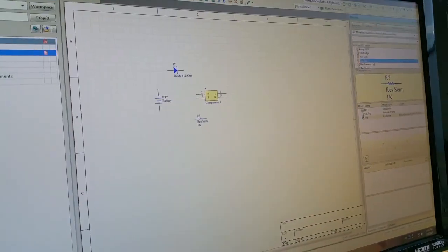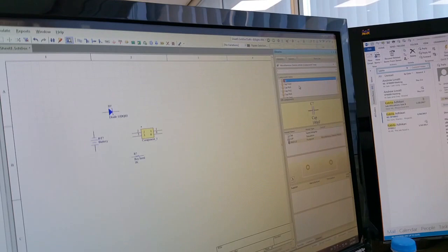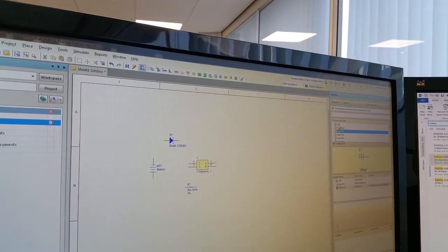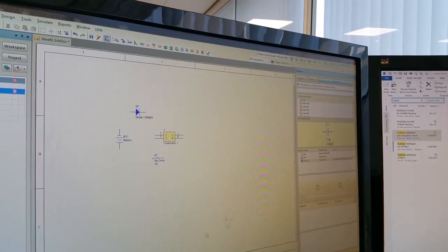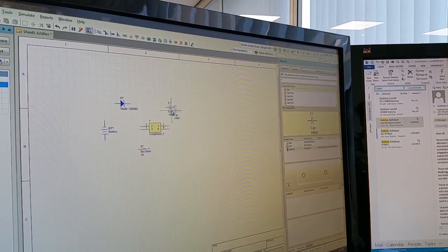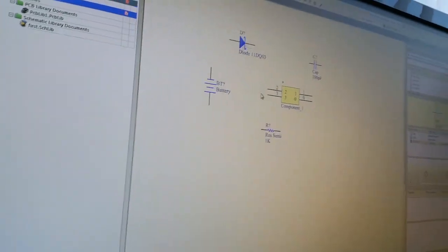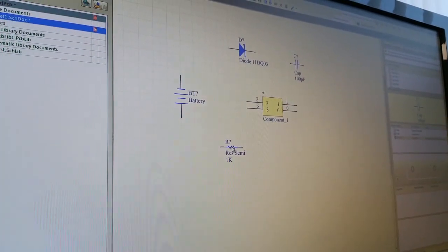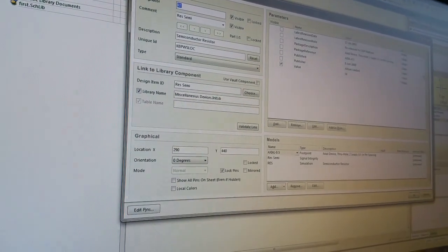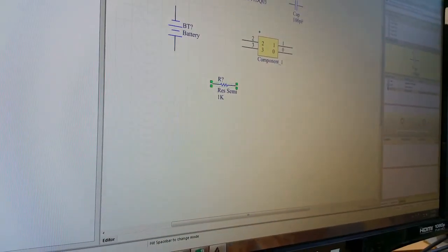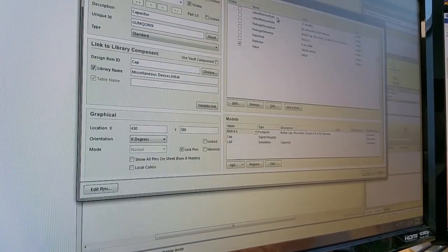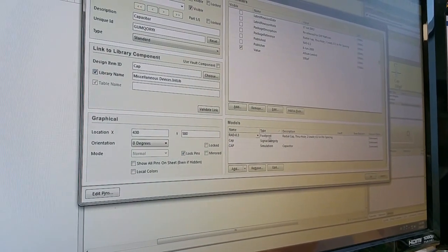and let's pick up the capacitor as well. Bring any capacitor. So the capacitors we have now, you see, are all big capacitors. I think these 4-5 components are enough for now. Let's connect. Before connection we will change the footprint for this one. Double click. Footprint. We need surface mount, for example, for that one. Double click, you can see the footprint.